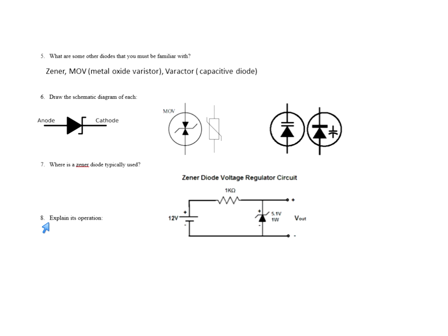So if I want a 5-volt Zener regulator, I would buy a 5-volt Zener. If I wanted to regulate this at 12 volts, I'd buy a 12-volt Zener. So the load is placed in parallel with the Zener diode. It's right here. This would be the load. Right, in parallel with the Zener diode. So a Zener diode conducts to limit its voltage across it to the Zener voltage.